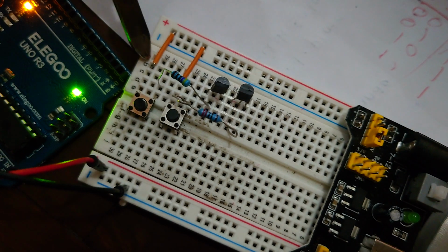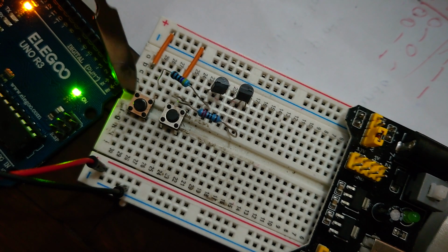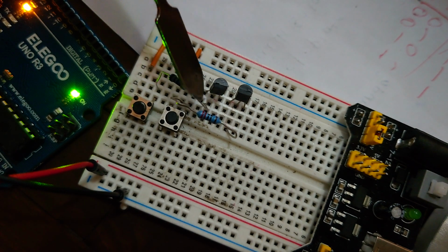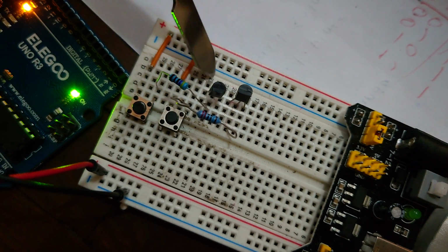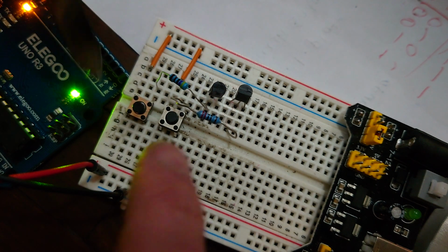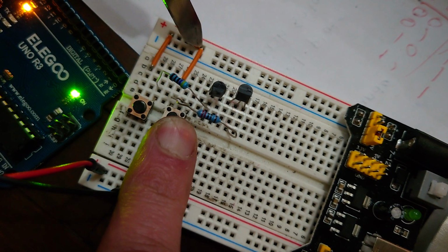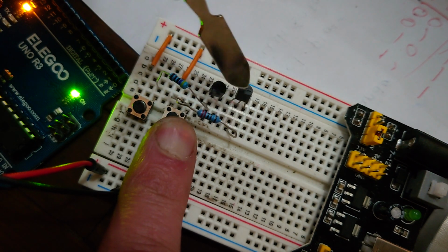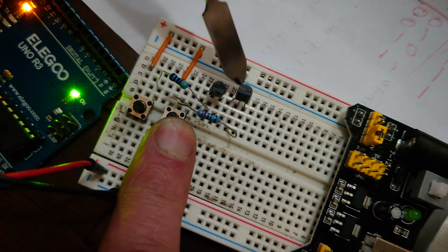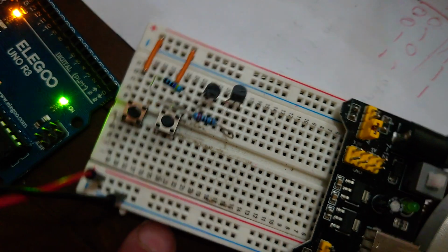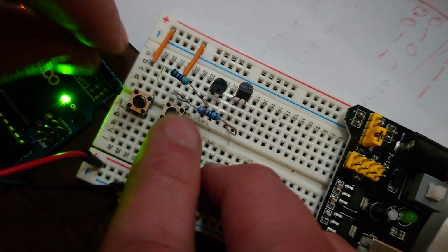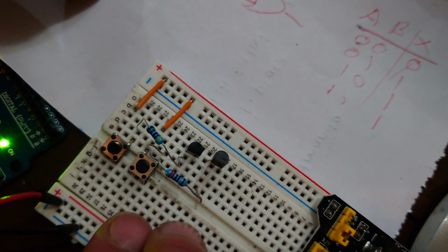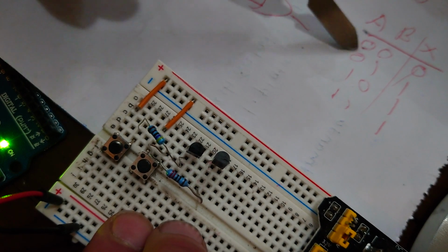These wires are quite thin on the resistors, but hopefully you can see. So the power is coming from here into the switch or button. The button, when I press it, is going to let the current flow through this one into the base of transistor A. Button B, on the other hand, is going to take its current from here. It's going to pass it through this second resistor and into the base of transistor B. So A and B over here. Okay, so that's our basic control setup. And A and B relates to these numbers over here. So off, off, off, on, etc.